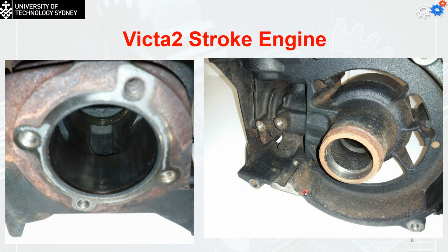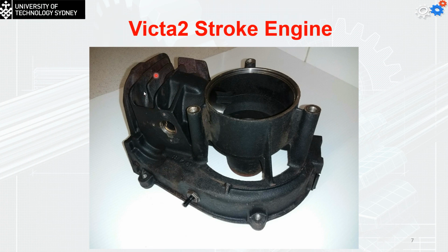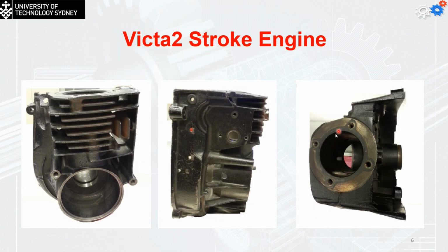The other details, like the internal cavities and the complicated shape of the fins, also tell you that this part has been made by an expendable casting operation. It's very hard to make such a shape using the die casting operation. I gave you a hint yesterday about how we can modify the shape of the part if you would like to make it with a die casting operation.